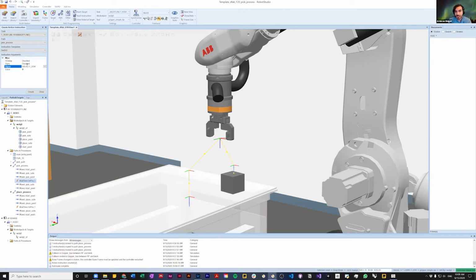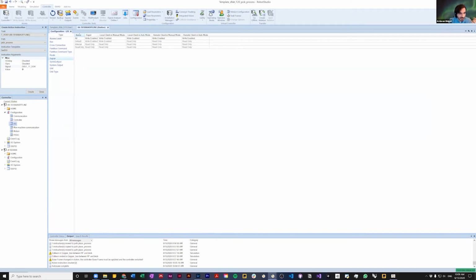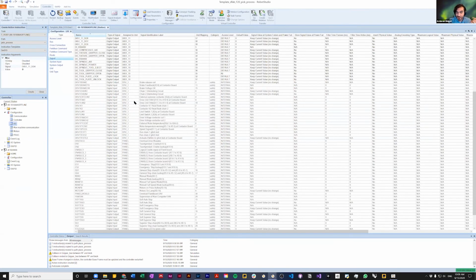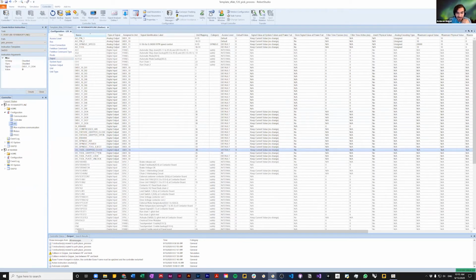And we need to make sure that we have selected the correct signal. To be honest, in this robot, we have too many of those signals. And if you want to see how many signals we have, I can actually show you. This many signals. If you open this part of your RobotStudio file, you will see there are lots of them here. But there are a couple of them that have meaningful names, like spindle power, spindle tool, tool gripper open, tool gripper close, and these two dangerous ones, tool plate lock and unlock, that hopefully no one is going to mistakenly take as these two.